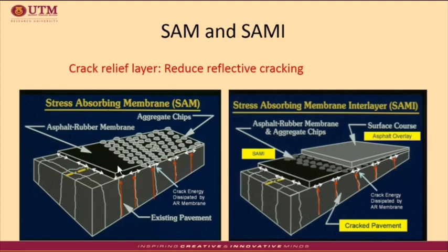In this case, the addition of crumb rubber in asphalt binder has increased the viscosity at high temperature to provide better resistance against bleeding, and is very flexible at low temperature to give better resistance to thermal cracking and fatigue cracking. Also, the rubber reduced the aging potential or oxidation rate.